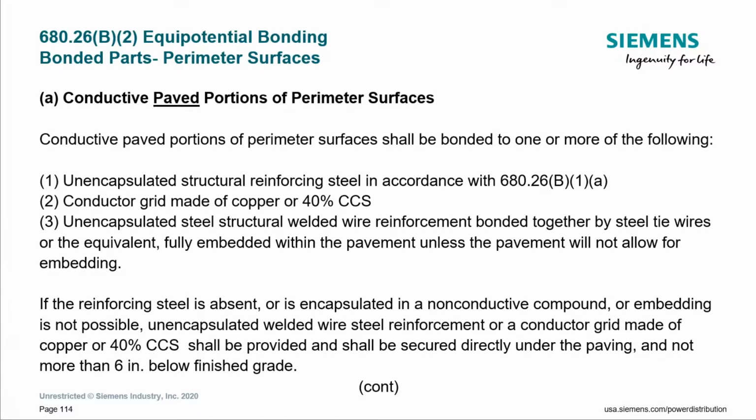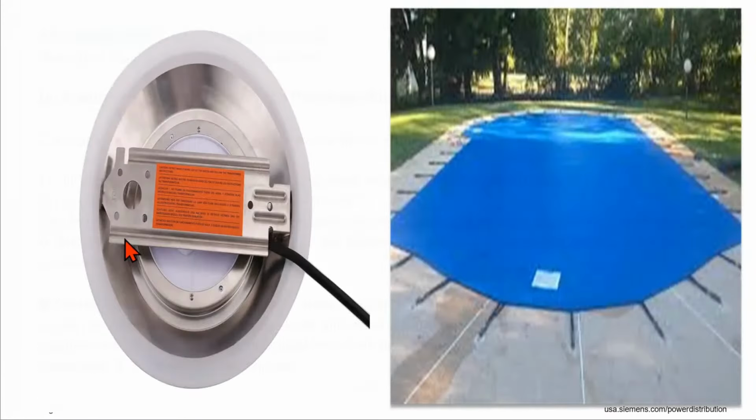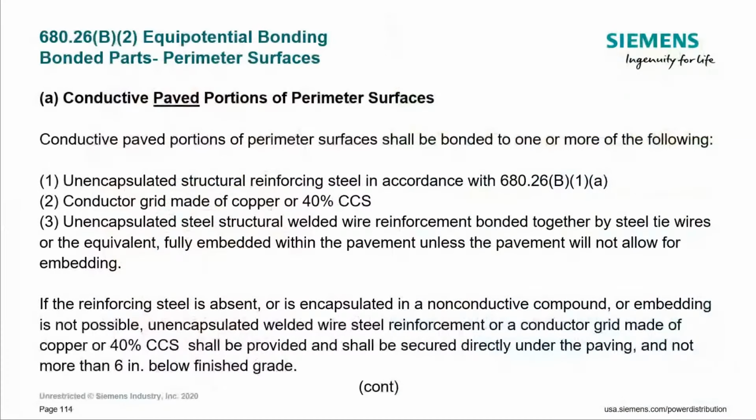Okay, but something equivalent. Me personally, and I've been asked this, if they used a split bolt to connect the wire mesh together, I would be okay with that, as long as it's listed for direct burial, going to concrete. Yeah, I would be okay with that.